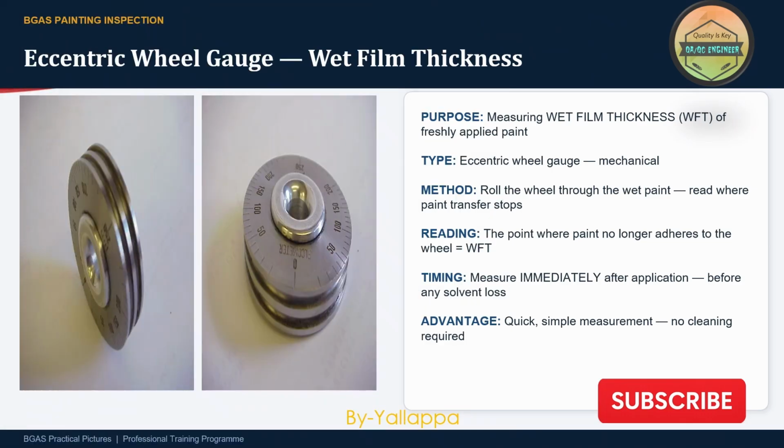This slide shows an eccentric wheel wet film thickness gauge. The instrument measures wet coating thickness immediately after application. Wet film measurements allow inspectors to predict the final dry film thickness. This enables corrective action before the coating cures. The gauge is simple, fast, and widely used during coating application activities.